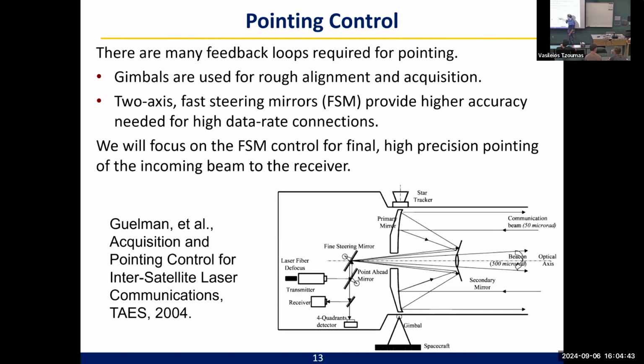These mirrors are partially glazed. So some of the beam comes down here and some comes into the receiver. There's a sensor here. So you're trying to keep the laser on the dot in the center of the dot. So I can measure exactly where the laser beam is, and so I can measure Y almost perfectly. That part isn't really the issue. And if this laser beam is not perfectly on the dot, I'm not getting all the energy going into the receiver.